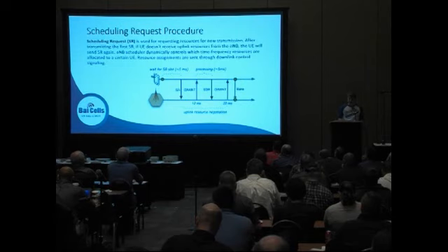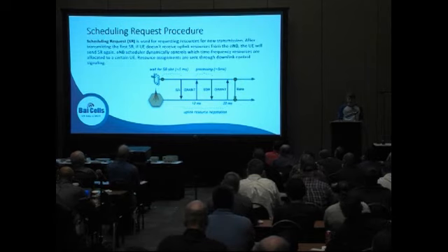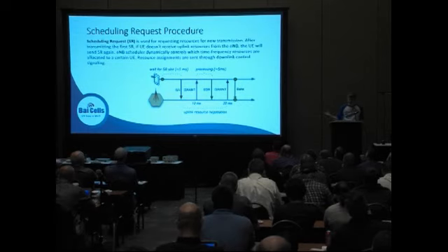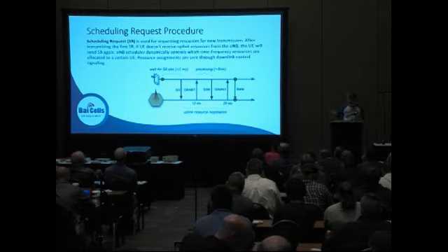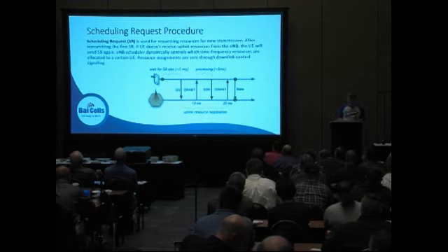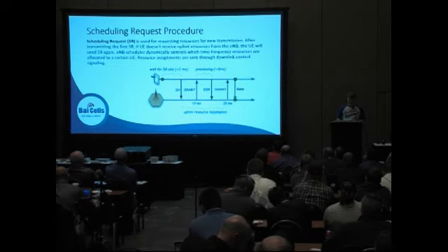We've noticed with a couple of operators that have higher interference issues that sometimes the UE might drop out, or bottom out, where there might be a period of time where it's connected, but it loses internet access. And this is one example of why that may happen. If there's high interference, there are potential issues where it might not be scheduled because the eNodeB is not hearing that right, or we'll talk about that a little later in detail as well.